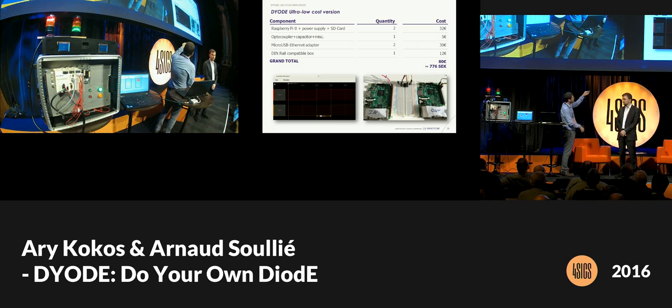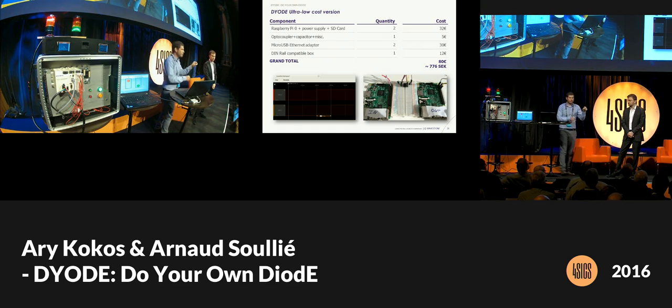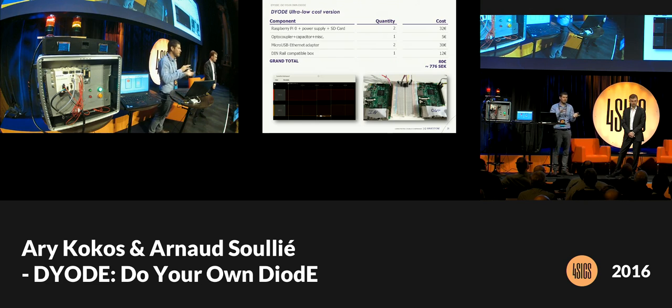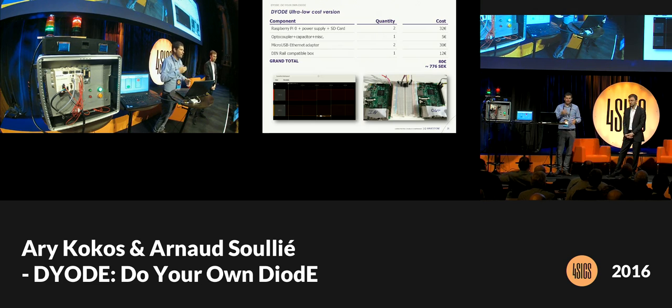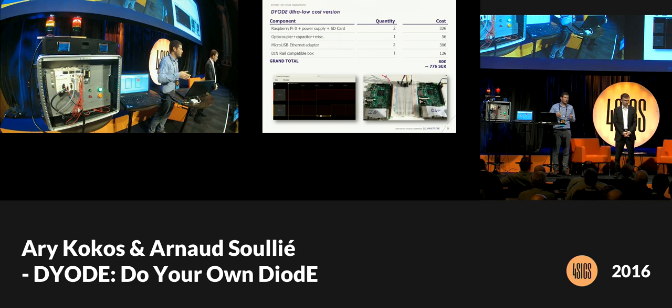And as you can see, we used, again, a logic analyzer that was plugged in before and after the optocoupler to see what kind of delay is induced by this component. It's about 10 nanoseconds. The problem is if you want to use a very high-speed serial connection, then the optocoupler will not follow along, and that's why we have the 20 kilobytes limit at the moment.